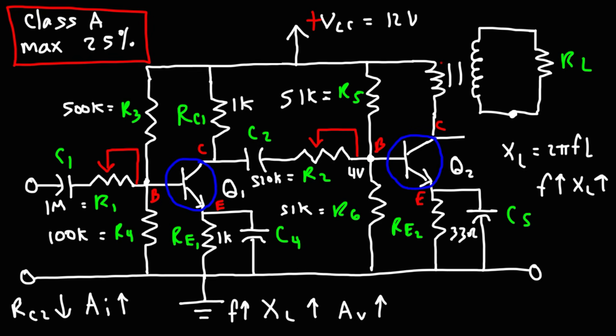So that's the one downside of using this transformer, it'll favor high frequency signals, but it will reduce the amplitude of low frequency signals. So you may get a more high pitched sound. But one advantage of using a transformer is the efficiency. The theoretical efficiency of a transformer coupled Class A amplifier is 50%. Now, in practice, you may get an efficiency of less than 40%, but nevertheless it is better than a regular Class A amplifier. And so you can get more power at the output.